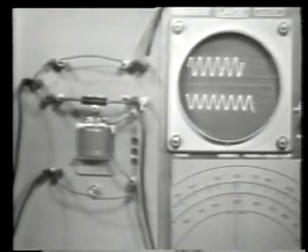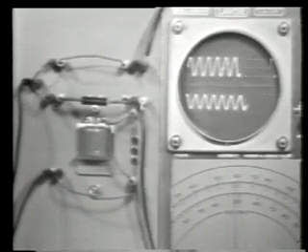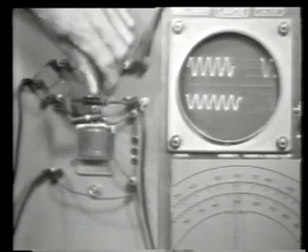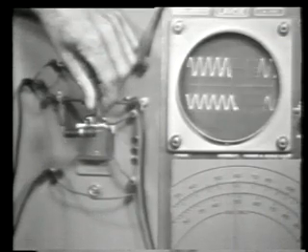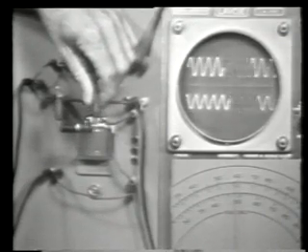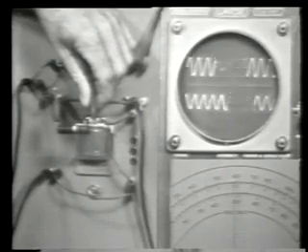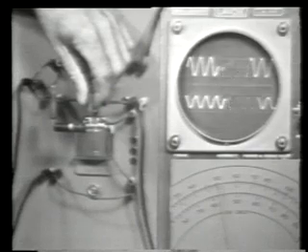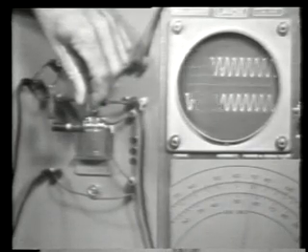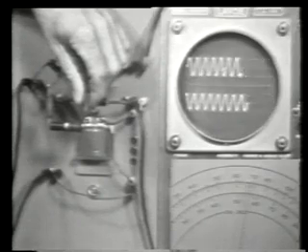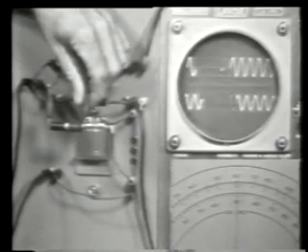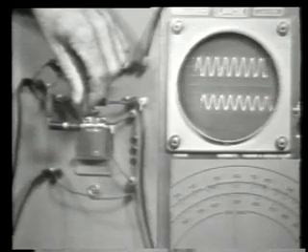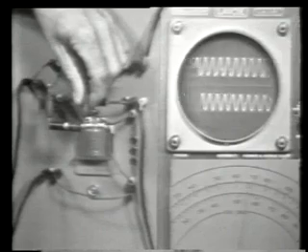Using this inductor and this capacitor, and with the addition of this resistor to the circuit, let's design a filter circuit that will pass a band of frequencies between, say about 500 hertz and 700 hertz, with a center frequency of 600 hertz. Now, we're only going to be passing this small band of frequencies. The rest of the frequencies we want to reject.